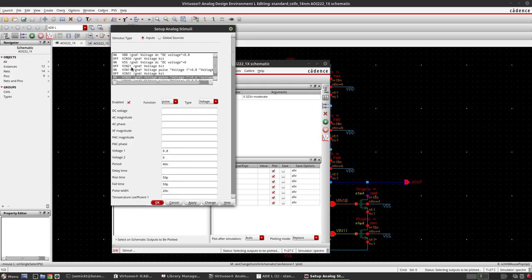Then I have to give V21. I will give pulse, voltage is 0.8, period is 80 nano, right? We had given how much? 40 nano there, right? So we will be giving here 80 nano, and rise time is 50 pico, fall time is 50 pico, and here the pulse width will be 40 nano. Apply, and then V21 is done.